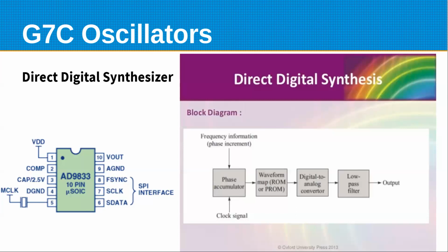You're just sampling the wave. Right. The samples are stored in there for many different amounts of phase. And then the clock signal is going to be some multiple of samples of your sine wave times whatever your output frequency needs to be that you want.